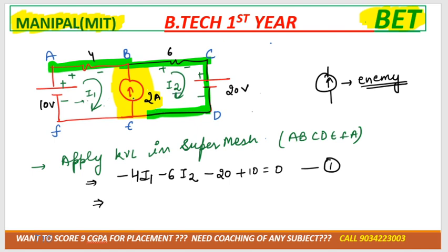So I1 direction and 2 ampere direction, same or opposite? Tell me. It's opposite, so I1 would be negative. Similarly, I2 direction and 2 ampere direction, same or opposite? It's same. Same direction means positive and opposite direction means negative. Okay, so you'll have two meshes, two variables and two equations. You can solve it.